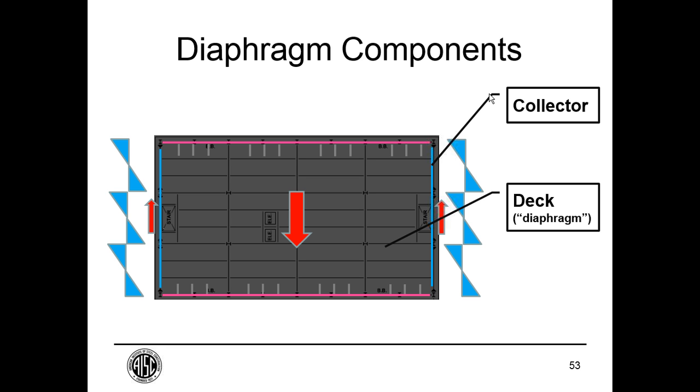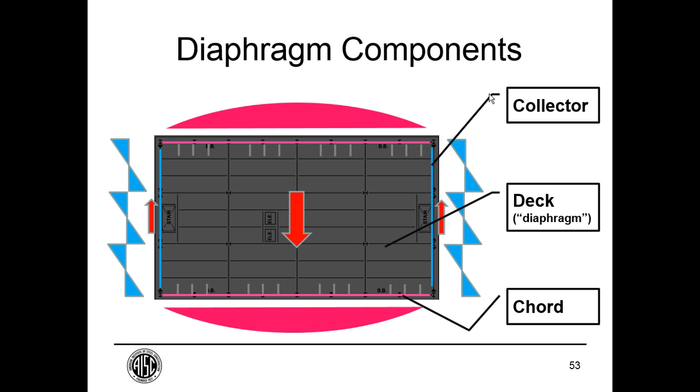And we also have the shear in the deck, not only loading the collector, but it's also loading the chords at the north and south. And as it loads those chords, it creates axial forces that have an axial force diagram that looks something like this.